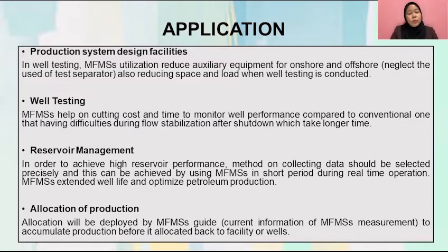And the second one is well testing. As we know, a conventional test separator is very expensive and also requires much time to monitor each well's performance. And for that, the time required to restabilize flow condition is also longer than usual. The disadvantage of using a test separator is that well performance may suffer after a shutdown cycle and it also requires more frequent workover. Thus, by using MFM, it will give more satisfactory measurement and can also monitor the well during clean-up flow phases.